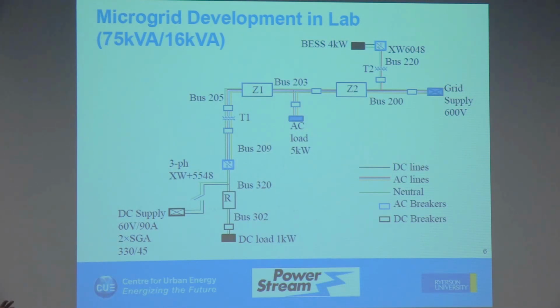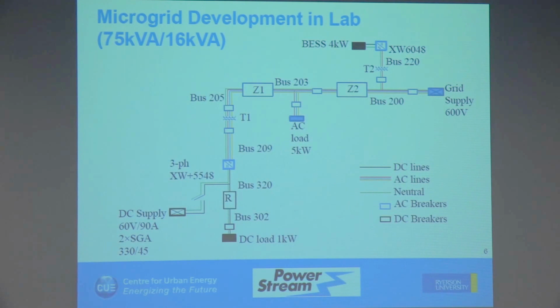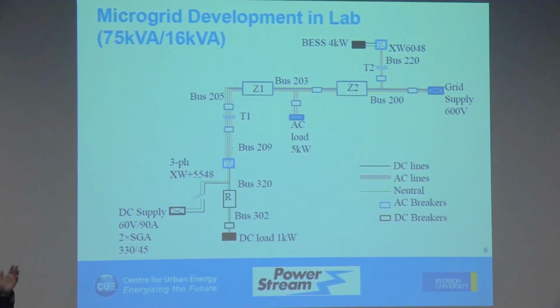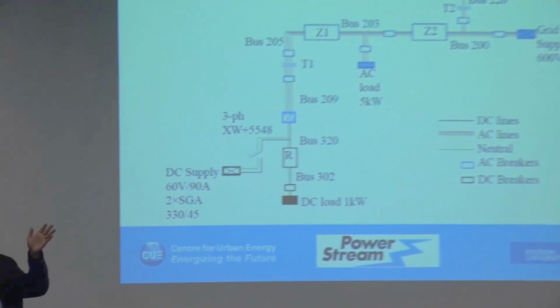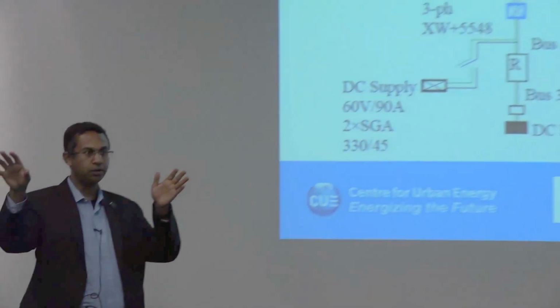So let me go to the next portion of the answer. If I have a system with a slack bus, demand, and wind generation, at no time can the slack bus become a demand. So you will size wind generation in such a way that it doesn't exceed the total load in the system. The slack generator will still be the slack generator, but its output will become zero. Is that okay? Does that answer your question?